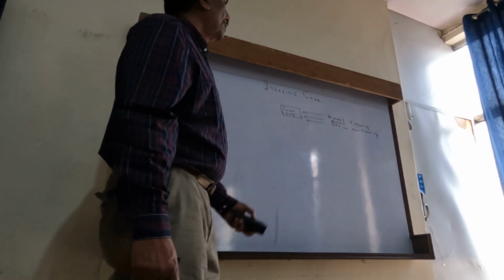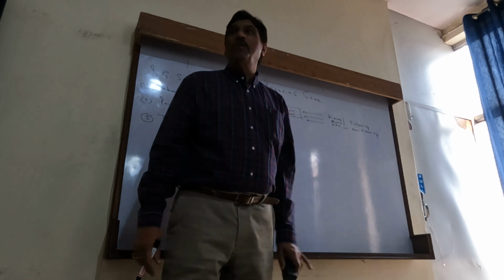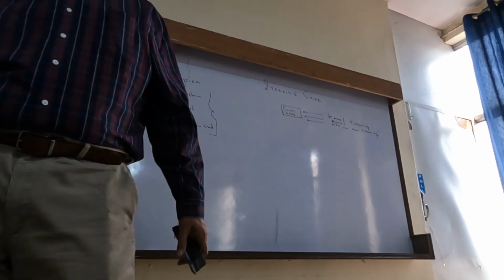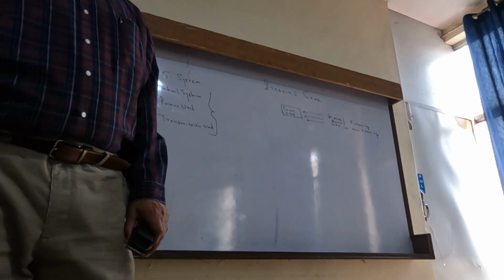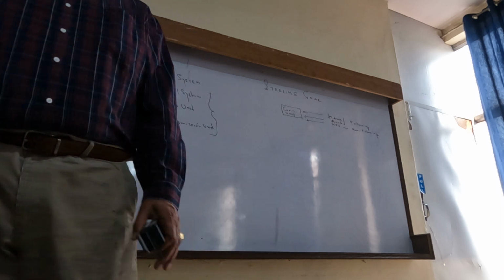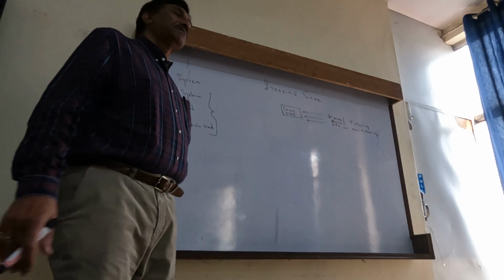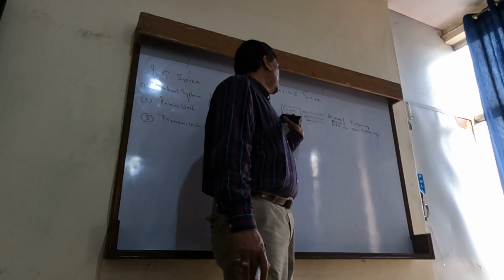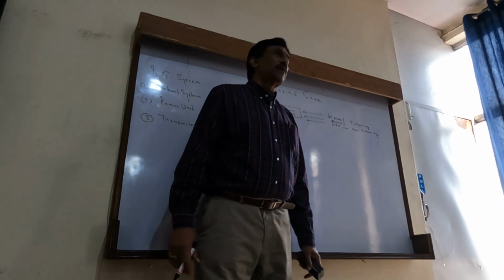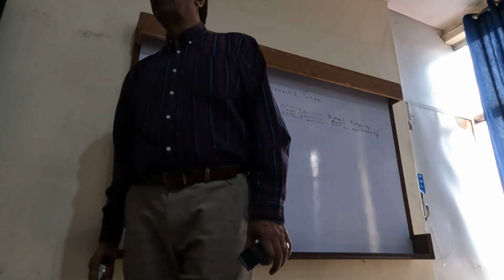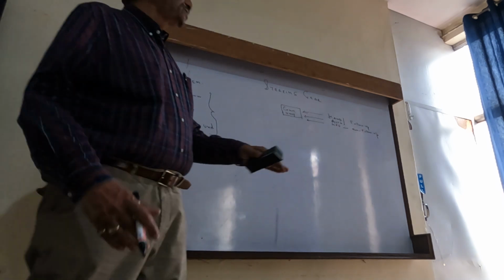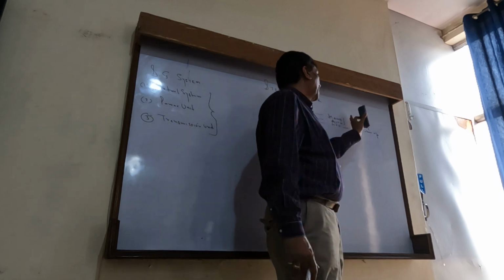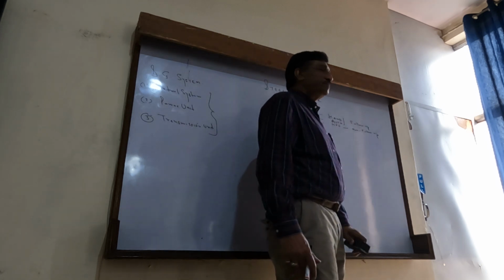Because in case of non-follow-up, there is no feedback. The control system does not know where the rudder is, that is, what its angle is. So therefore we are having direct control from the bridge, irrespective of whatever may be the angle. The control system cannot process the signal simply because there is a failure. Right? We will see what the failure is, but we have these three different modes, primarily called follow-up and non-follow-up.